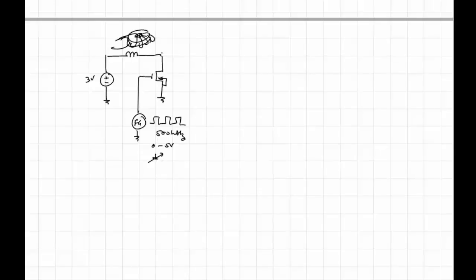Okay, and then you'll use a 1N4148, basically a little signal diode. And the goal here is that we want to light up some LEDs, some white LEDs, 3 of them. Now nominally they're about 2.8 volts each, so that means you're going to need at least somewhere between 8 and 9 volts to turn this on.